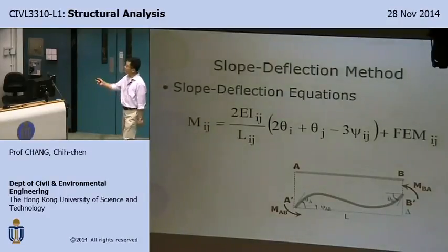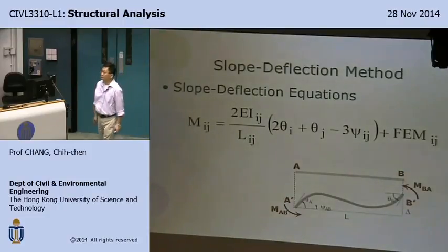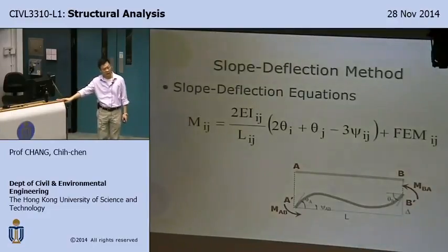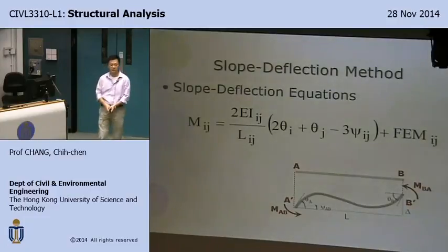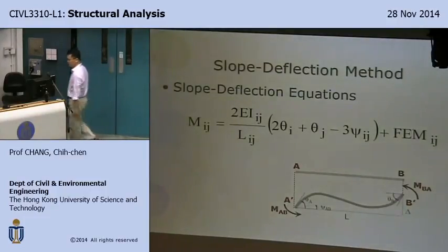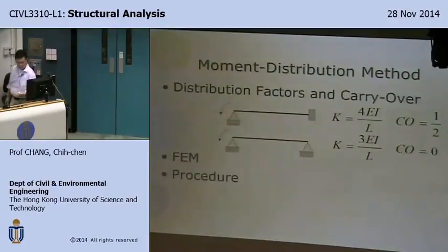All right, that makes sense. So in my own notation, I assume that everything is positive if they are counterclockwise, and negative if they are clockwise. But that only helped me to calculate. So when you go back to plotting the moment diagram, or shear force diagrams, you still need to follow the definitions.